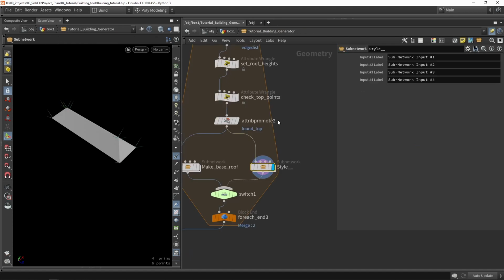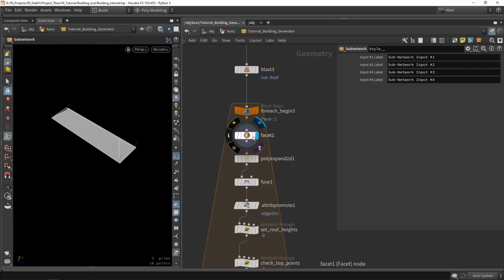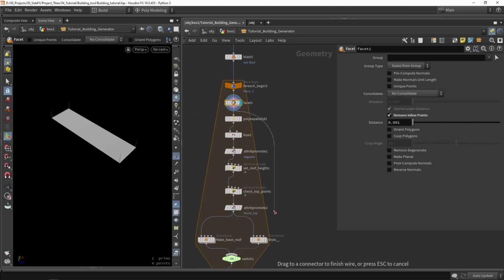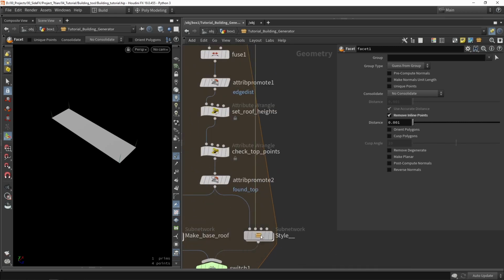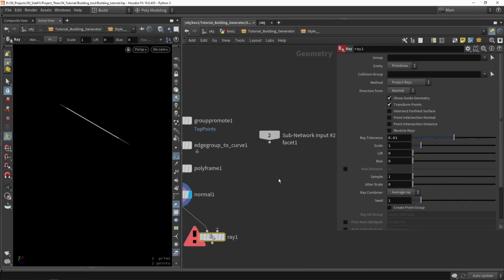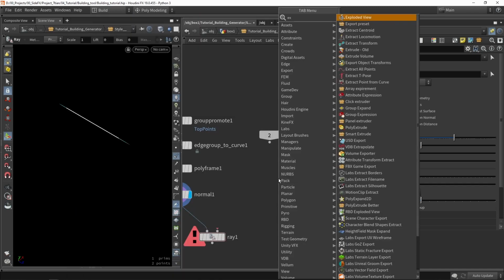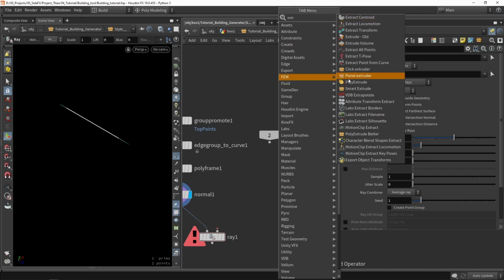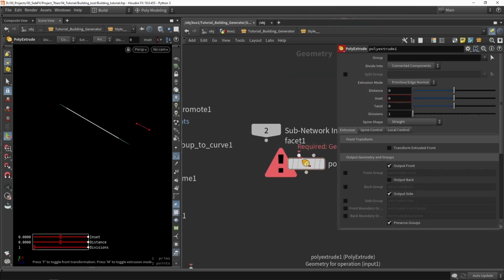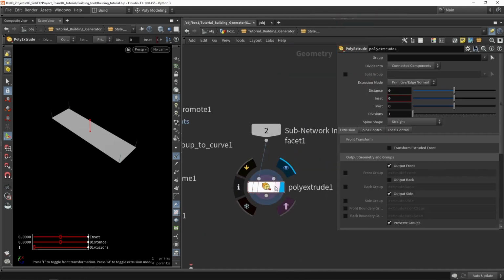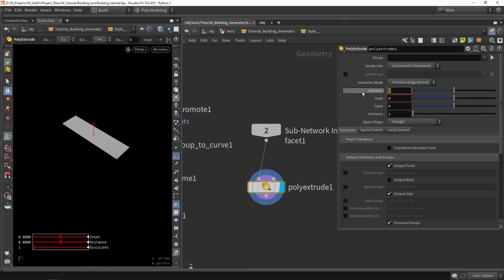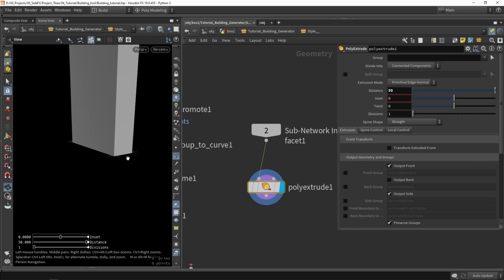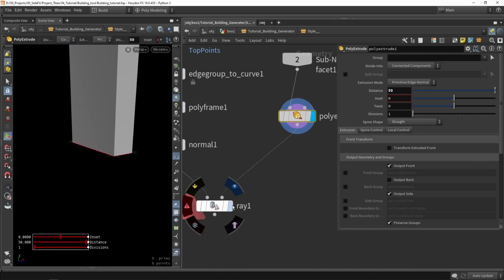What if we could just grab, for example, our base shapes after we did that cleanup? So here we can just say like so. We now have access to that base shape, and we're just going to simply do an extrusion on that. So here, a poly extrusion, and fill it in like so. We're going to fill in a value like, let's say 50, something that's pretty large. And with that, we can now do a raycast.